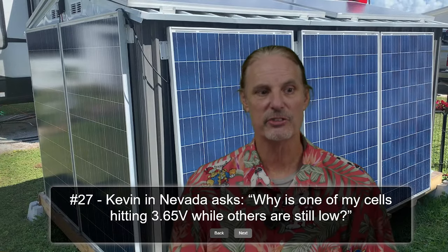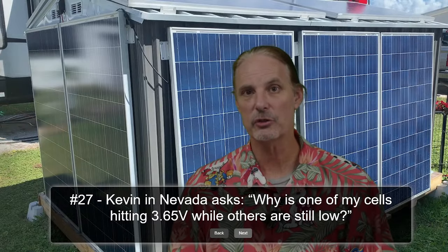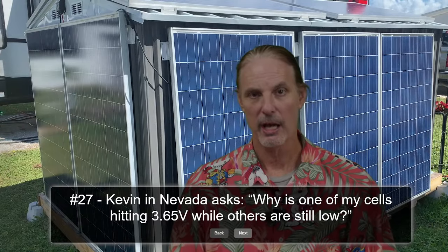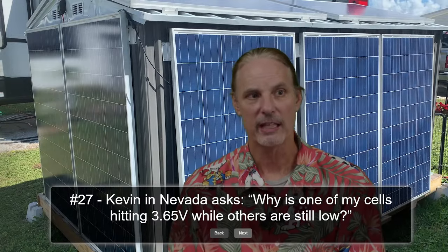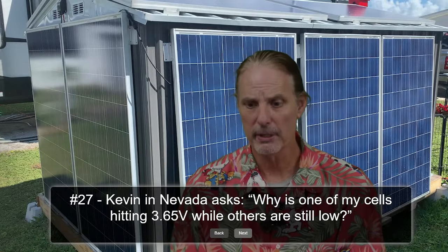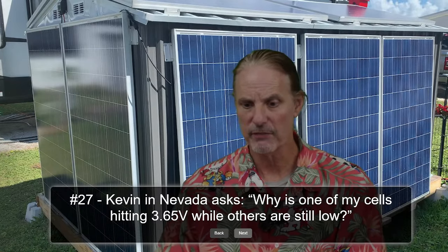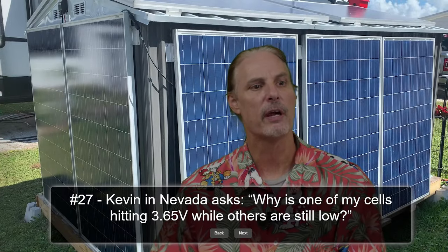My guess is that you're trying to charge too high too fast, and the easiest way to work this is to basically start with a lower voltage and give the battery time to balance a little bit, and then you can specifically handle it from there.